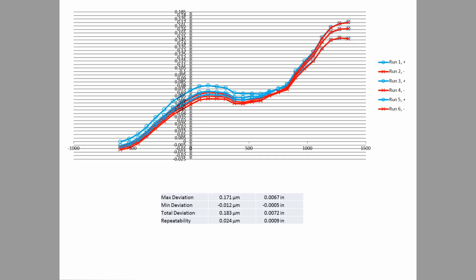So let's say we apply a comp value which is perfect for this middle point. We'll say that that's 160 micron. So I apply a comp value of 160 micron. If we get a test run which is exactly the same as our middle run again, it comps out beautifully. If I apply 160 micron of comp to my bottom line, then I get a negative value when I run this for verification. I've applied too much comp. And if I look at my top one, I've applied too little. This is the problem with repeatability.